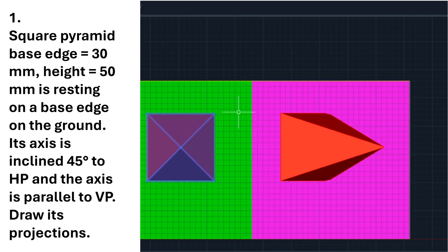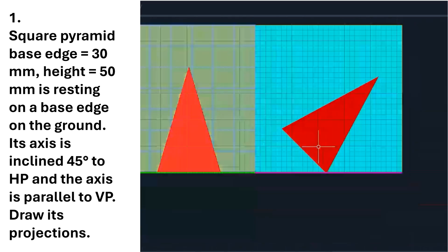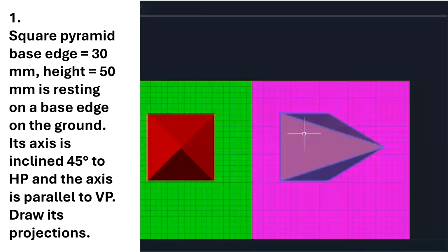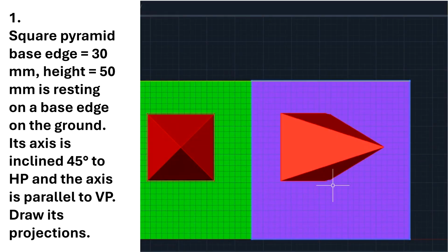Then you see in the top view, I already told you, so we can go to the front view, and now we need to draw the top view. When you want to draw the top view, you take the leftmost corner and rightmost corner and draw a line. That means all the faces above this will be visible. So this face will be visible, and all the outside edges will be visible.